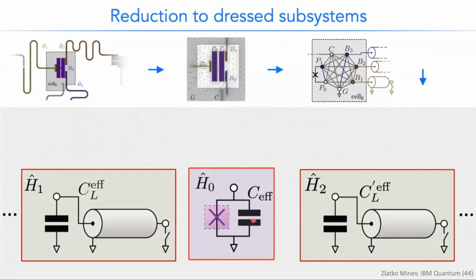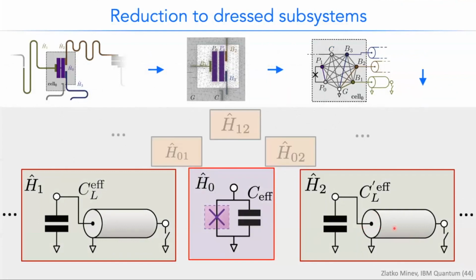So you have this very tight connection. You're not guessing the capacitance values here. And it tells you the dressed, loaded resonator line parameters. It also finds the interaction Hamiltonians between the qubit and the readout, the qubit and the other resonator, the readout and the readout. It does all of these different parts together.